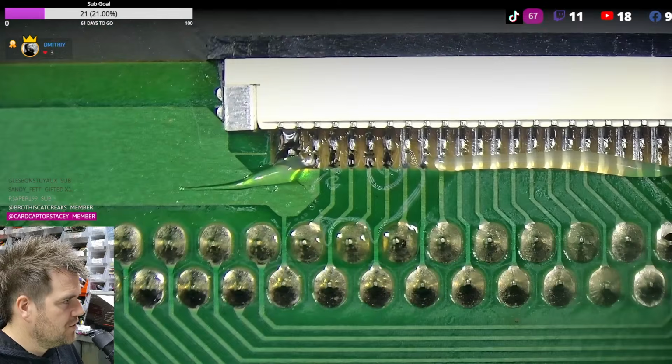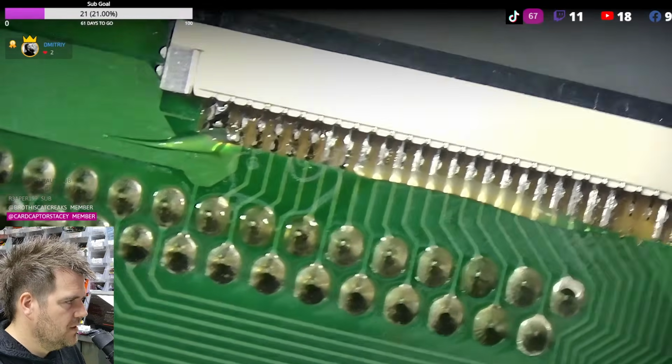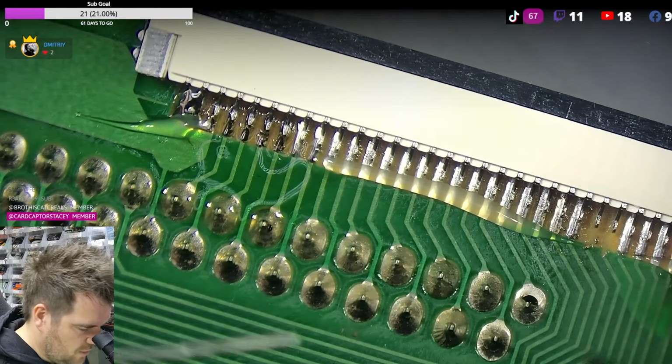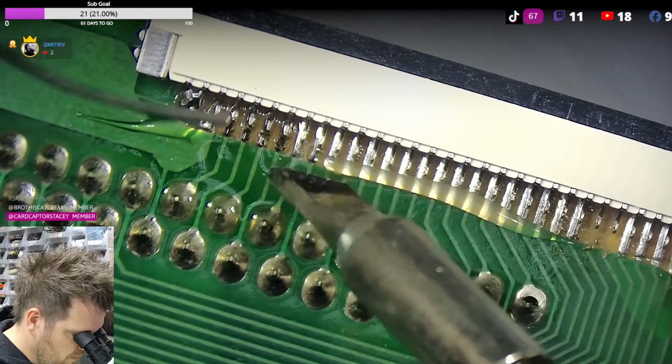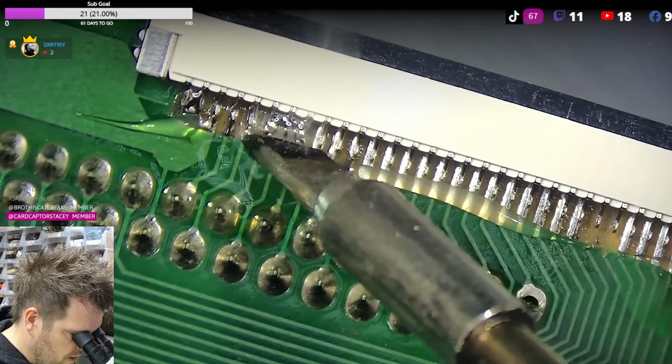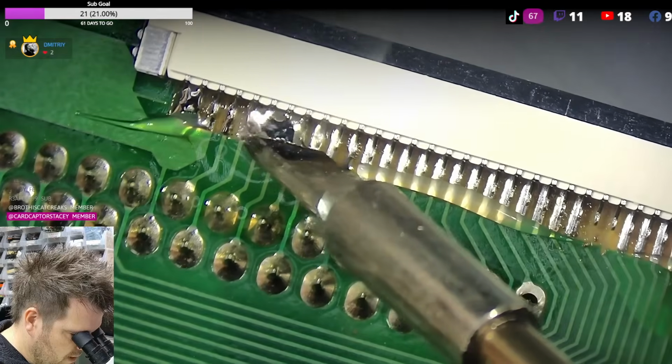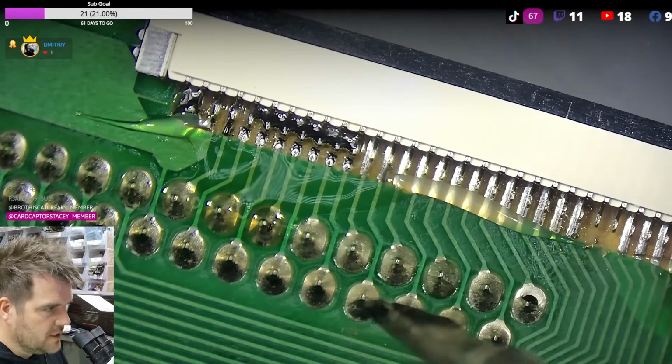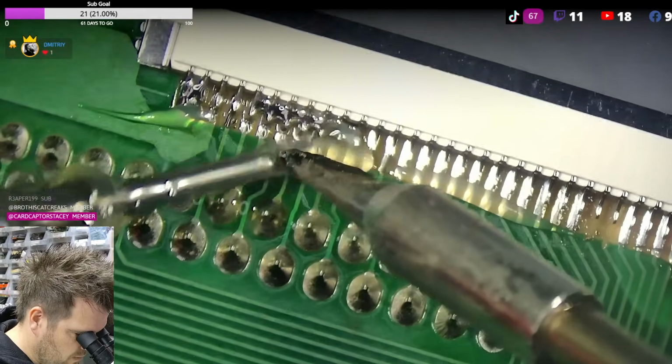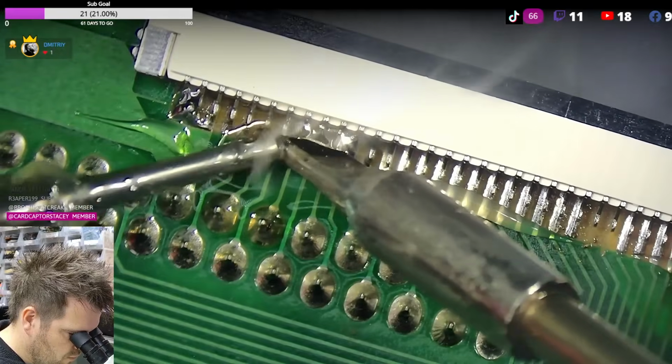What you can do, though, on most connectors, some connectors just have a pitch that doesn't suit this method, but what I tend to do is just drag solder. So let's give it a go. Just flood your iron with solder, get a big ball on the connector and just drag down slowly. And if you see it's already bridging, flux on, go back up, drag down.